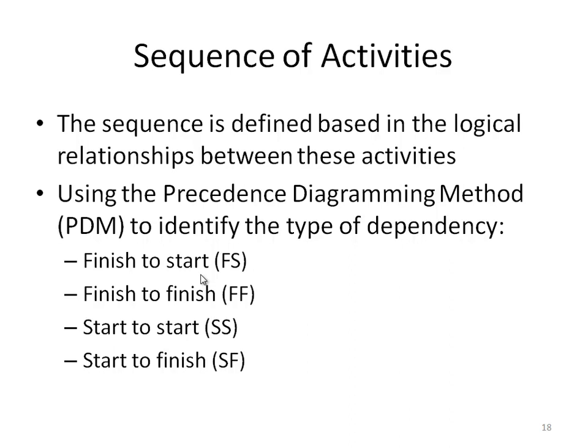We have 4 different dependencies that we can relate to: finish to start, finish to finish, start to start, and start to finish. Finish to start means that the initiation of the successor activity depends upon the completion of the predecessor activity. Finish to finish means the completion of a successor activity depends upon the completion of the predecessor activity.